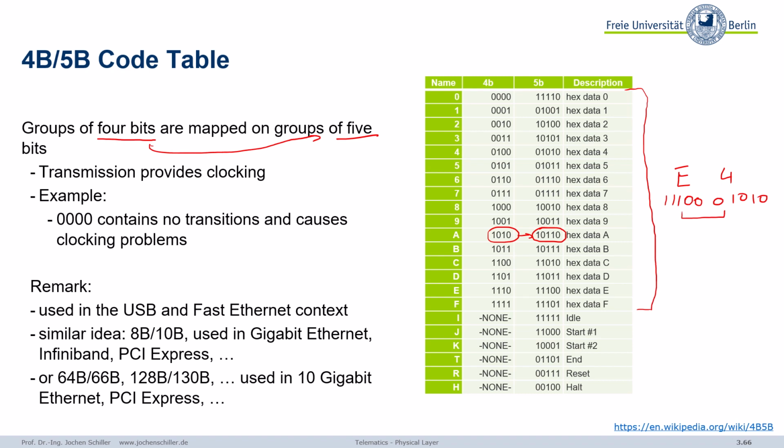So no matter what data you have, you can now use your non-return to 0 in this differential way. For example, you avoid the zeros. Perfect. So we can always have enough information for clocking, for the synchronization. Plus, and this is just a part of them, there are some more code words here that represent something special. For example, end of transmission. You can even cut the wire, then it's only zeros, and this also indicates to the receiver, oh, okay, now it's quiet, nothing is going on.